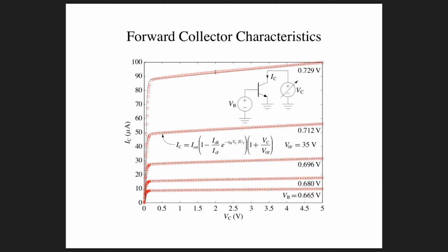Well, that was the thermal voltage UT times the natural log of 10, which is about 2.303. And so that times 25 millivolts turns out to be really close to 60 millivolts. And so there is a so-called 60 millivolt per decade rule for bipolar transistors, where if you change the base emitter voltage by about 0.06 volts, you change the current by an order of magnitude.